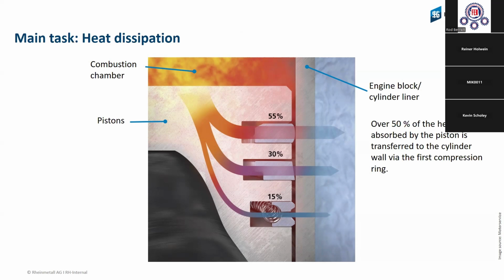It's important that the alloy piston is not higher than a temperature of 360, and it can get very complicated when we have more than 400 degrees. That means we must regulate the temperature of the piston so that it will not be too high. And this is also the job of the piston rings: to take the heat from the piston to the surface of the cylinder liner.